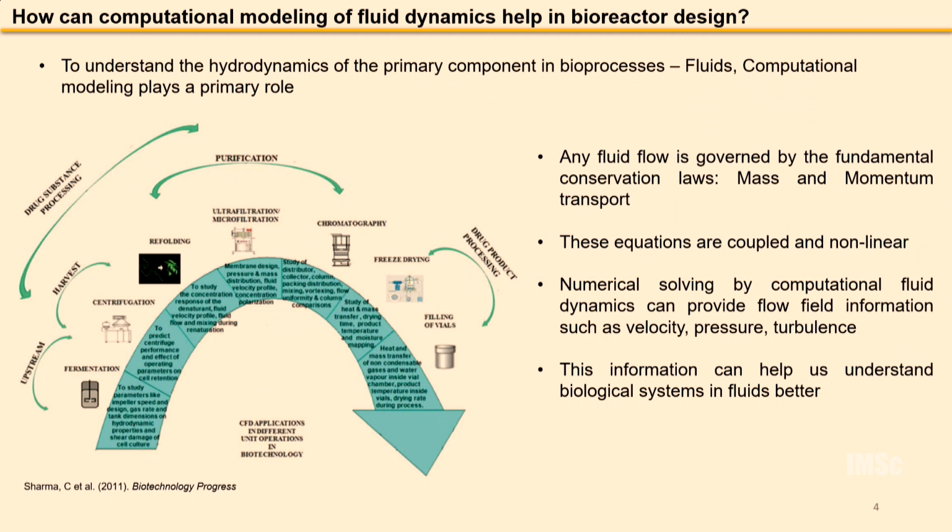Firstly, computational fluid dynamics is a technique where the fluid flow governing equations such as the mass, momentum and in some cases energy transport are solved numerically, because these equations are non-linear and coupled. This numerical solving helps us provide flow field information such as the velocity, the pressure and turbulence prevailing in the system. This information can help us understand the biological system better when we look into computational modeling.